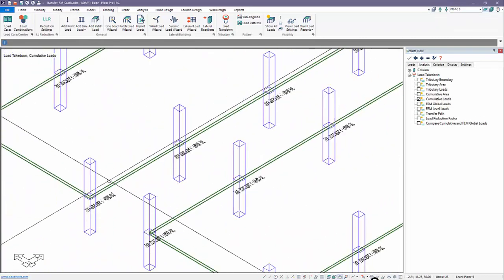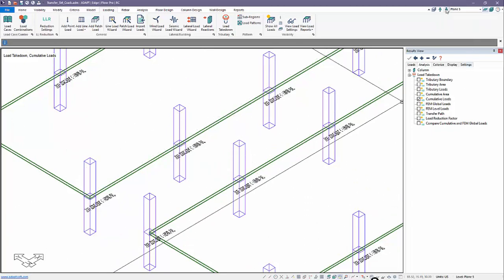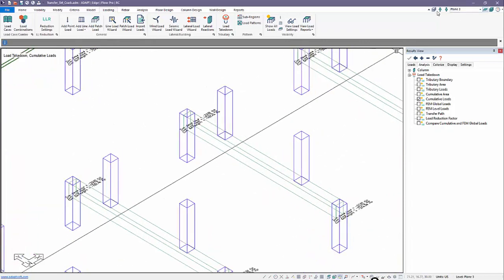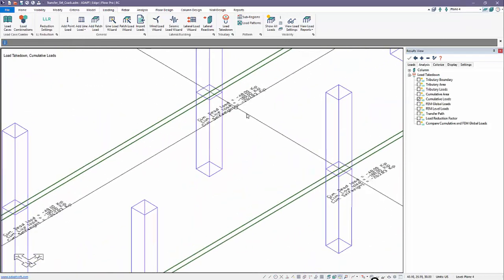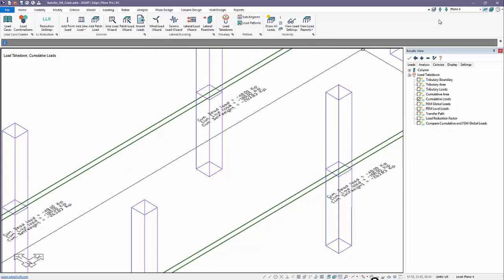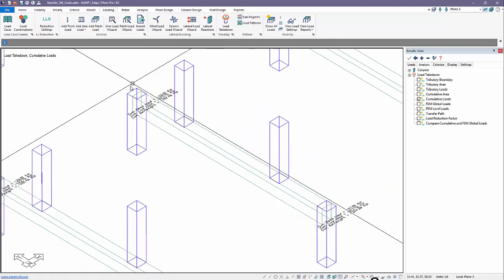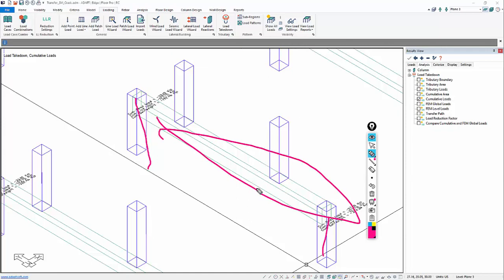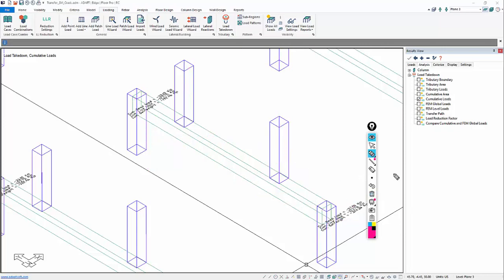So these inner columns on the split slabs above are what will be transferring load out to these beams. So when I go from this level 4, this set of loads, 48, 180, 263, that actually gets split, and ultimately it will end up down in these columns. But we want to evaluate these beams in this level. So this just gives us the ability to then use those reactions in these columns when we analyze this one floor in isolation.